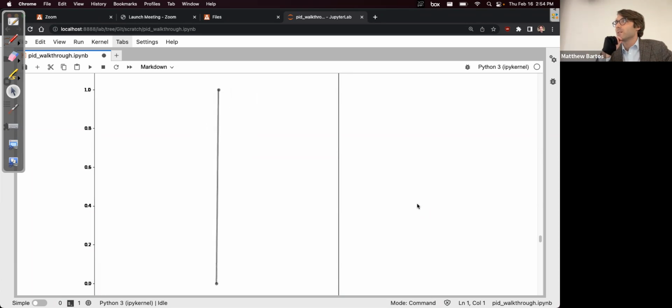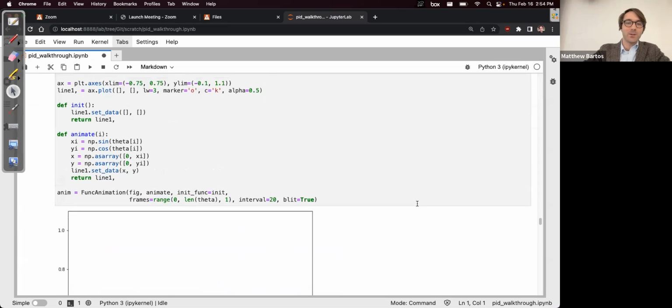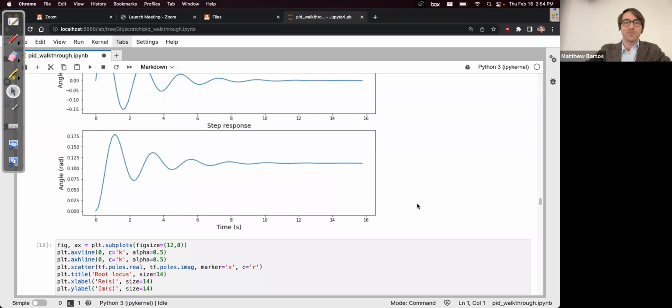So typically when you're doing control problems like this, you would just treat your initial conditions as being like an impulsive input occurring at time 0. Essentially, the two are equivalent. When you're simulating a system like this, you can also input the initial conditions if you want. When we're computing those closed loop transfer functions, though, we're just computing it with respect to an arbitrary input, and your initial conditions can be thought of as a type of input occurring at time 0. Okay. And I can show you how you can include initial conditions for these simulations as well.